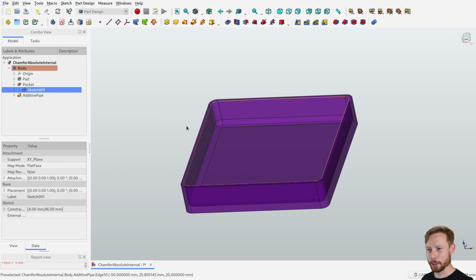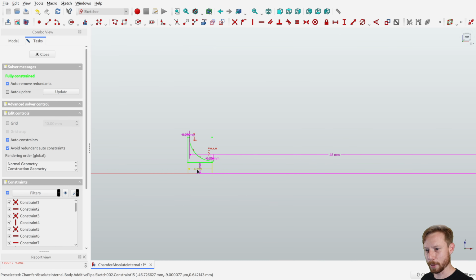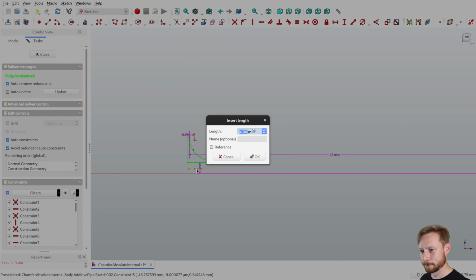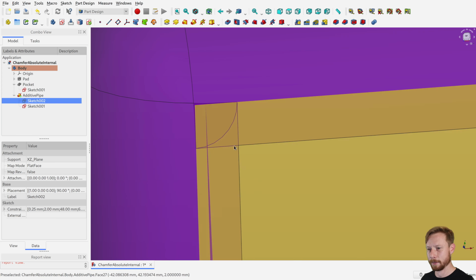And if I go and change my fillet profile to something that is larger than that value, so 4mm corner, so we'll make this 6mm. And yeah, now we have broken geometry, so we can't move forward with this model in this state.